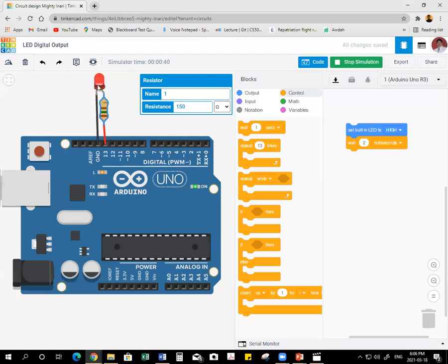Now see, brightness is increased, right? Now if I take 100 ohms, okay, this is also good because we are giving 5 volts. Next, if you want to decrease some more, let us take 50 ohms. No, we have a warning, 26 milliamperes. So we can have 75 ohms. Not enough. So take 100, no problem. So this is the digital output, but my explanation is not over.